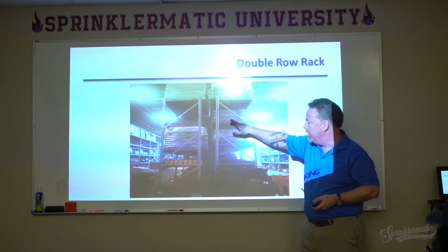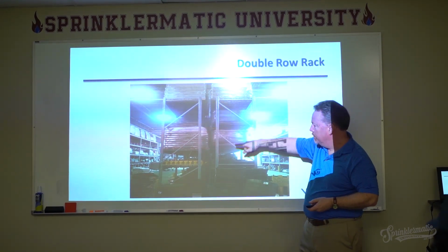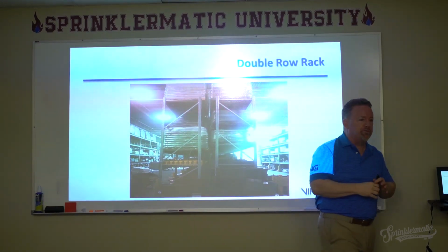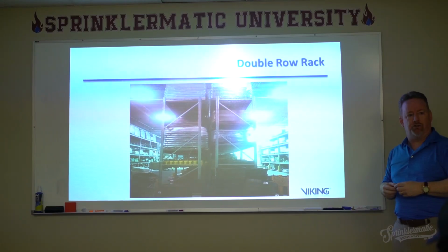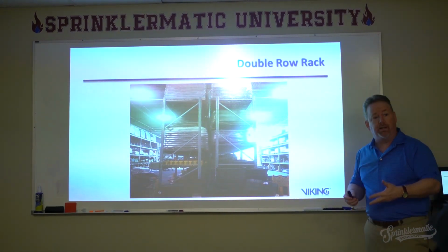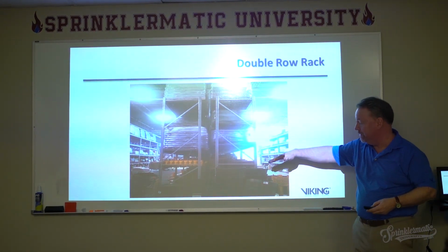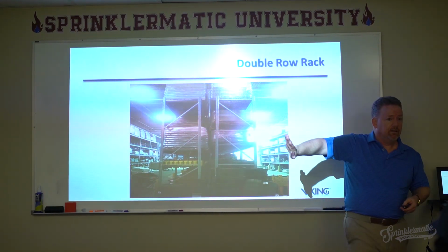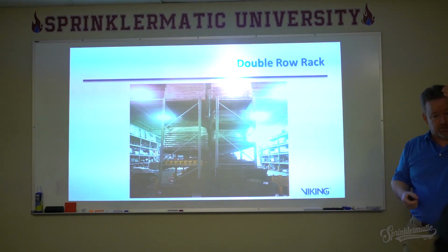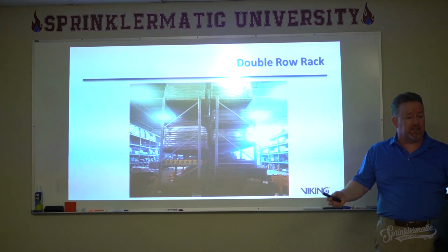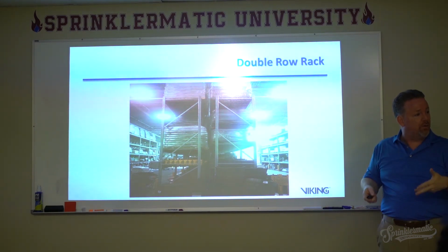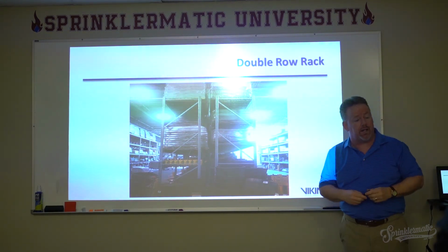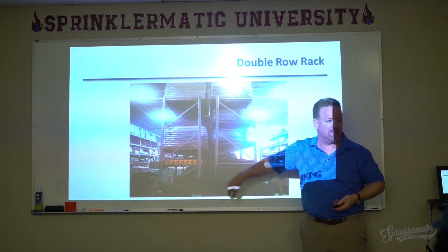Not only do we have air moving around all of this, but we've got air that can move down the flue spaces between the two racks. So there's a lot of capability here, possibilities for that fire to grow. Also, because it's so large and because these are pretty solid units, it's a bigger challenge to get water down through them. So not only are we getting a lot of air, fire and heat going up, it's a bigger challenge to get water back into these spaces.